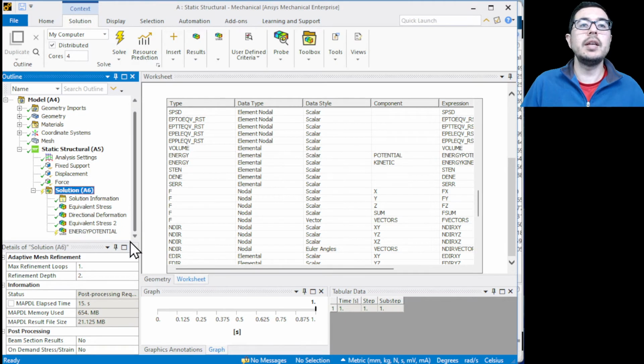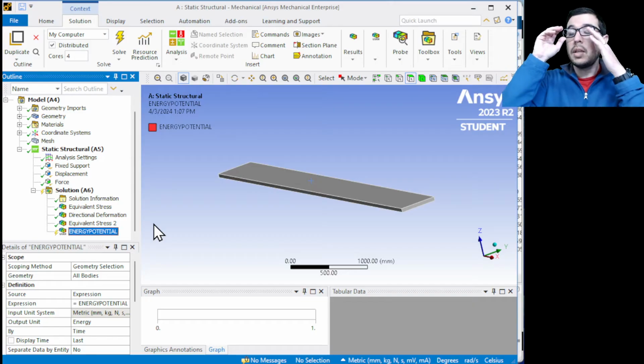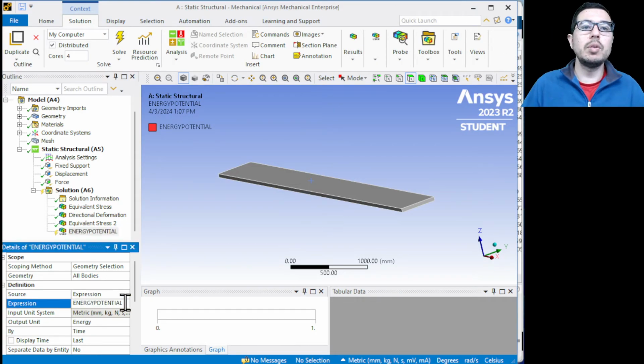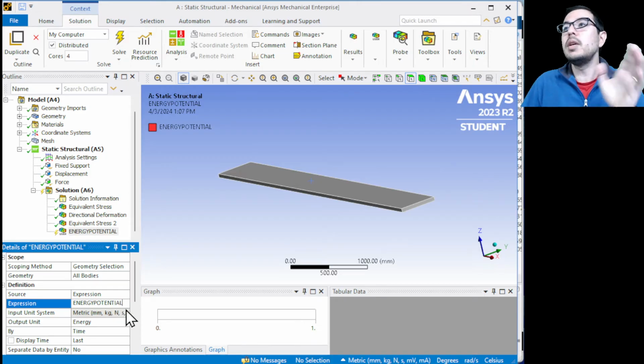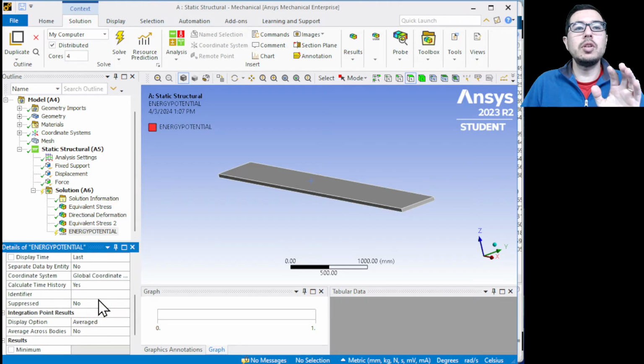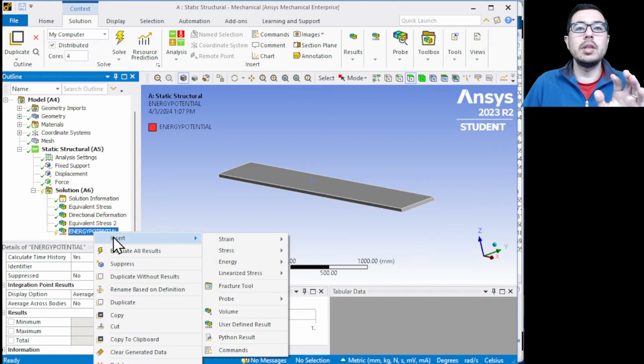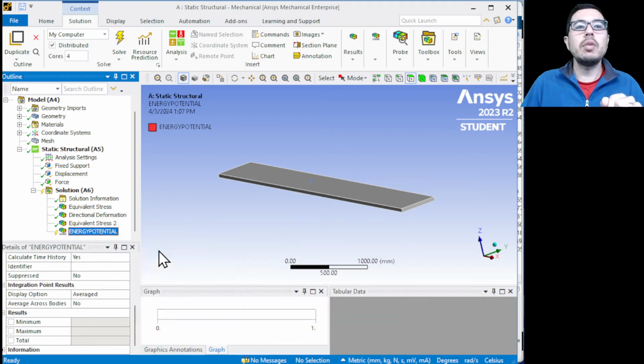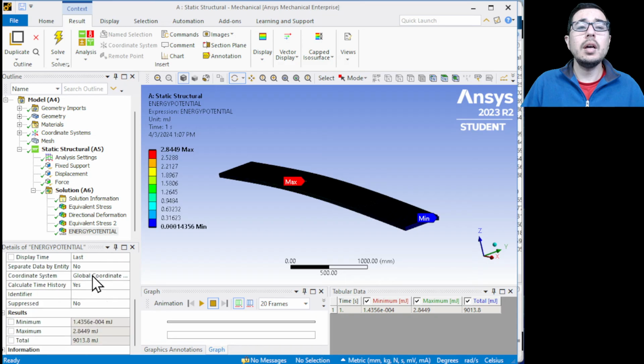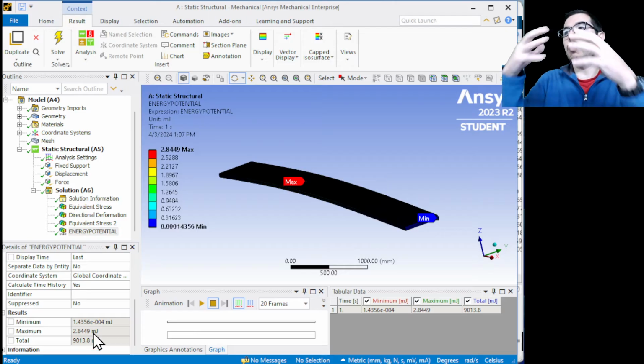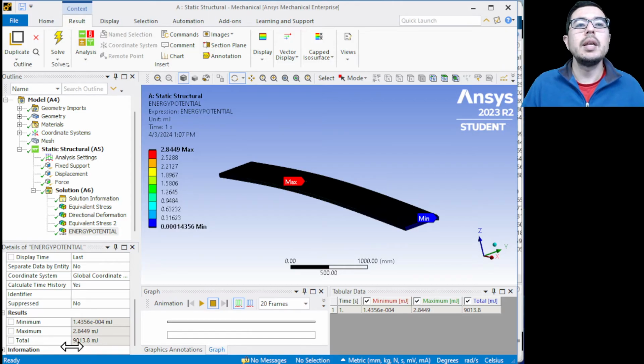So this is kind of fun. And so a UDF allows you to do more custom things. Like I can multiply now this quantity by 1,000 if I like. All right, it's going to come in millijoules, but I'll do that in MATLAB later. But I just wanted to show you that this is a possibility to use these UDFs. So here we're going to evaluate this result, and that comes out to tell us that the maximum is the total. Sorry, we want the total strain energy, not the maximum. The maximum will be the local strain energy in an element. The total is about 9 joules.